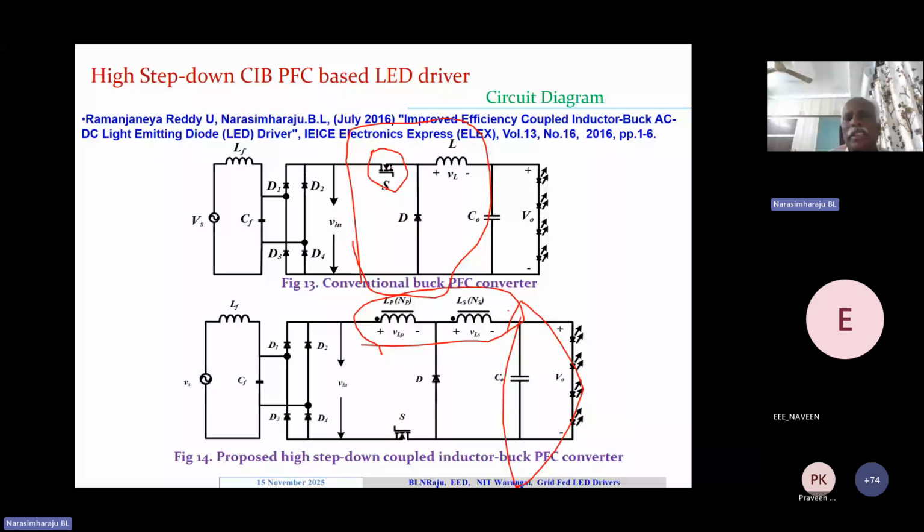The device gate is floating, between source and gate. So there is no proper reference for this gating signal in the buck converter. Moreover, if I connect this switch here, in this spot along with the coupled inductor, there was another issue which we have experienced.